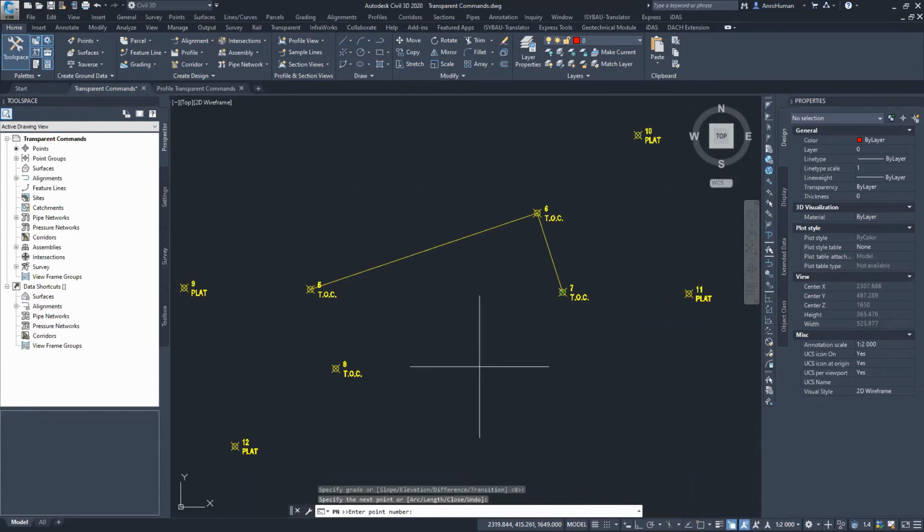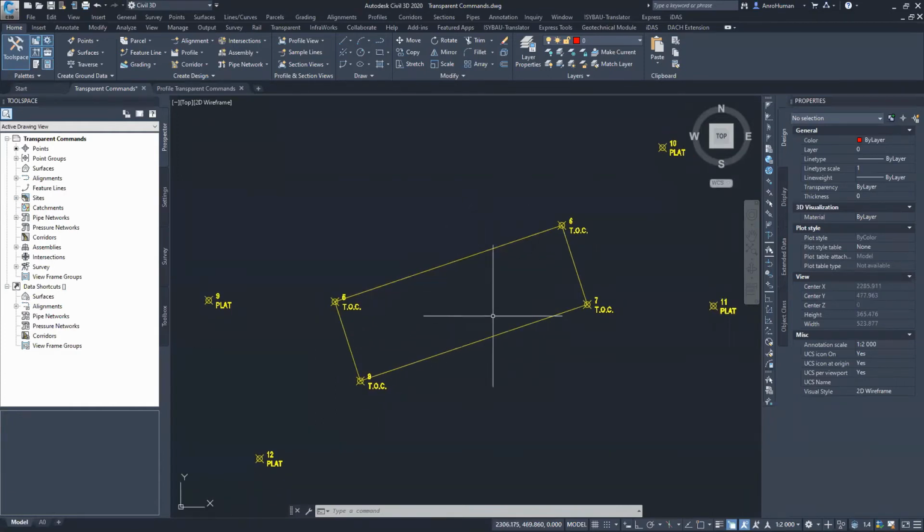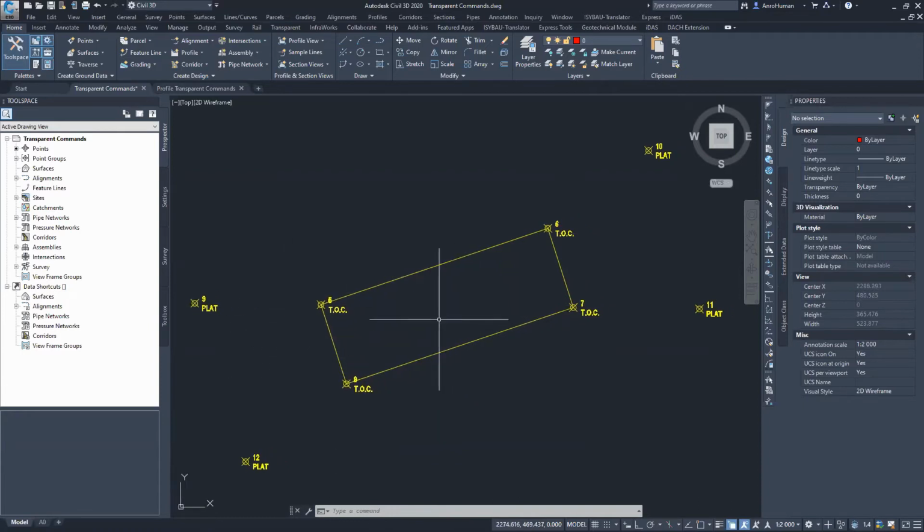Then I want to go back to 8. Press enter, it catches that slope, positive up in that direction. I press enter once again to grab that slope, and then 5, enter, and it closes up that object. Okay, so then I'm going to show you another way to achieve almost the exact same end goal with a feature line, but just with another way of choosing the points. So let's get started with that one.